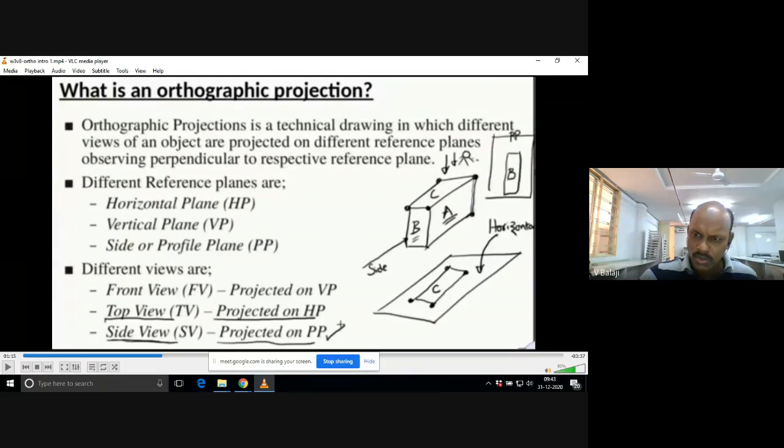Now I would like to give one more introduction, to isometric projection. Instead of drawing the front view, side view, and top view, three different views, why can't I draw one single view? You are looking at this object in a single view, and it has length, width, and height. I am representing all three dimensions in a single view. This view is known as the isometric view. If I require the front view, top view, and side view separately, then I have to draw like this.